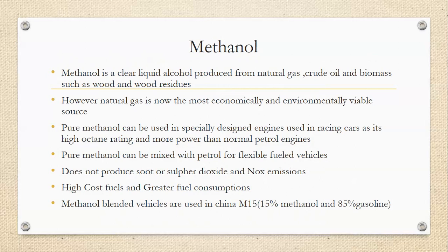This pure methanol fuel can be mixed with petrol for flexible fueled vehicles. This methanol fuel does not produce soot emissions, sulfur dioxide emissions, and NOx emissions, but the cost of this fuel is high and it consumes more fuel. Methanol blended vehicles are nowadays used in China in the ratio M15, 15 percentage of methanol and 85 percentage of gasoline.